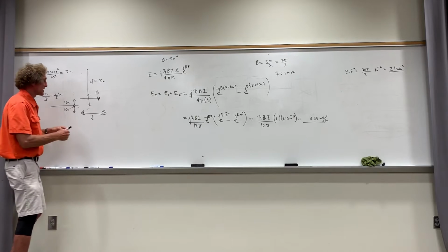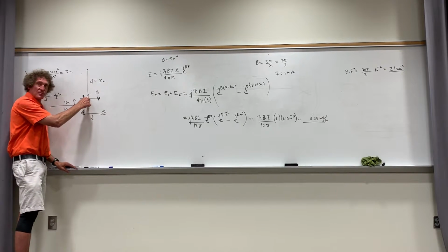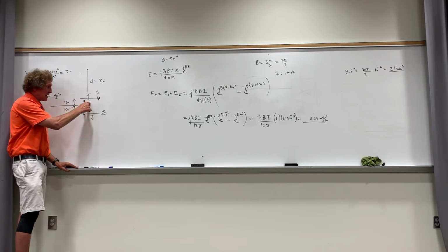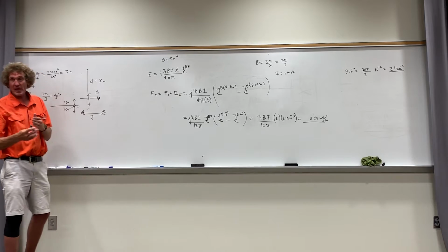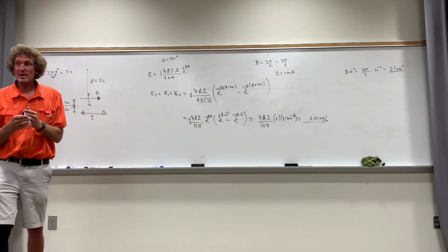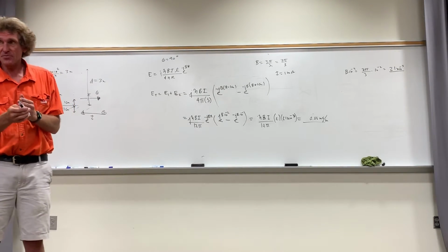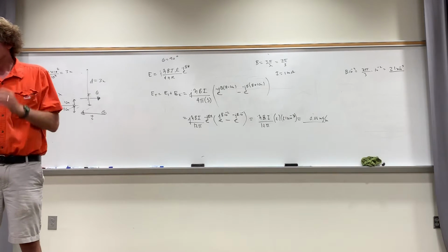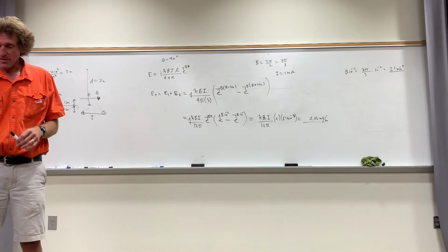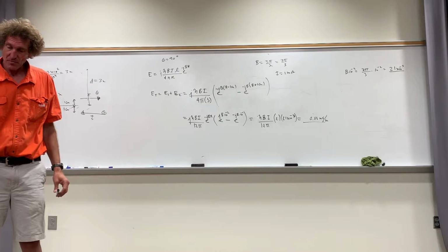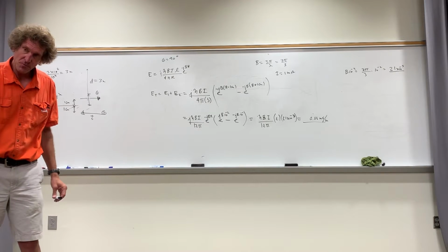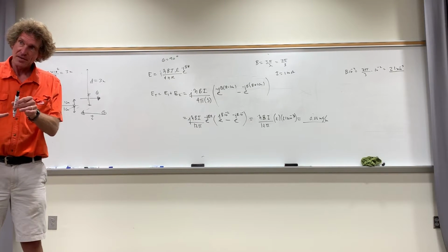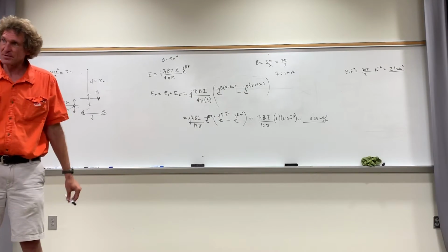And what you can think of is like this. The electric field launched from here, coming down, hits this ground plane, has a phase inversion, then keeps going straight up. If it adds constructively, you can get up to twice the electric field, and if it adds destructively, you get zero. So that's the one thing, when you have a wire over a ground plane and you're measuring the electric field with that antenna, as you move away, you'll hear peaks and then zeros, peaks and zeros, peaks and zeros.